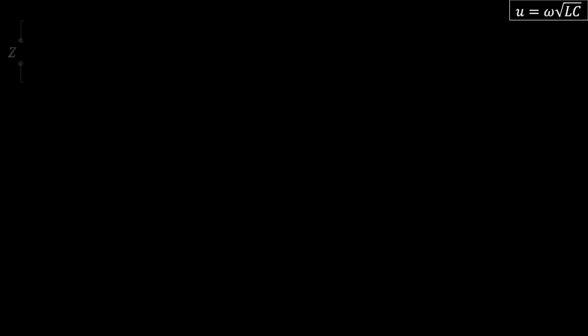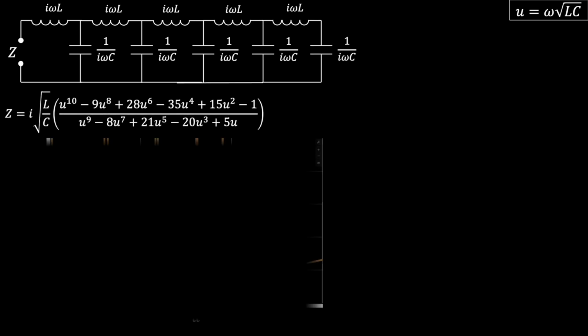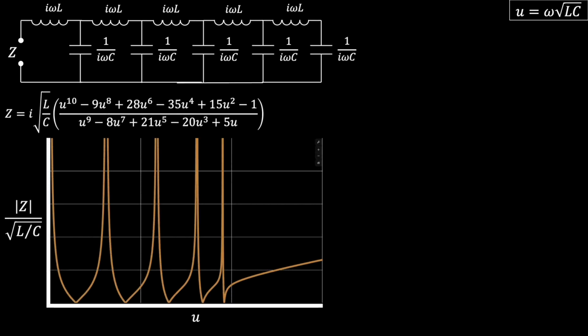So all of the examples so far have had the same value for each inductor and capacitor, but now I want to show what happens when some variation is added. Here's a ladder circuit with 10 elements. Again, all inductor elements are the same and all capacitor elements are the same. The impedance chart shoots up to infinity at infinite frequency, but that's a minor detail here.